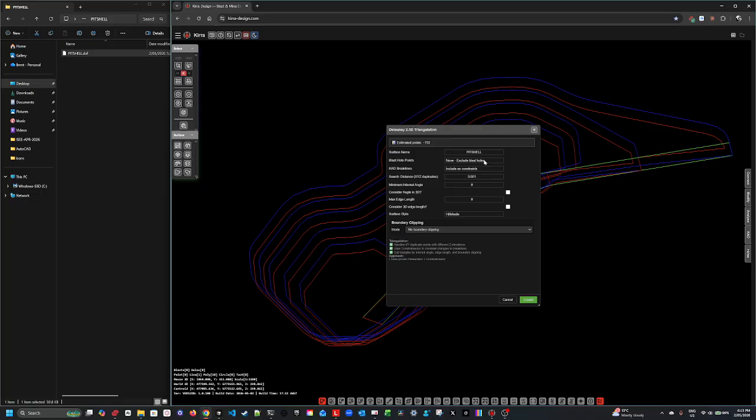We don't have any blast holes, but that's going to be fine. We're going to exclude those. Going to include these as constraints. Now this is important. Force triangles onto the edge. They're break lines or constraining edges. So it forces a triangle to share the edge of one of these lines. We don't care about duplicates and all that sort of stuff. Pretty much that's all we need.